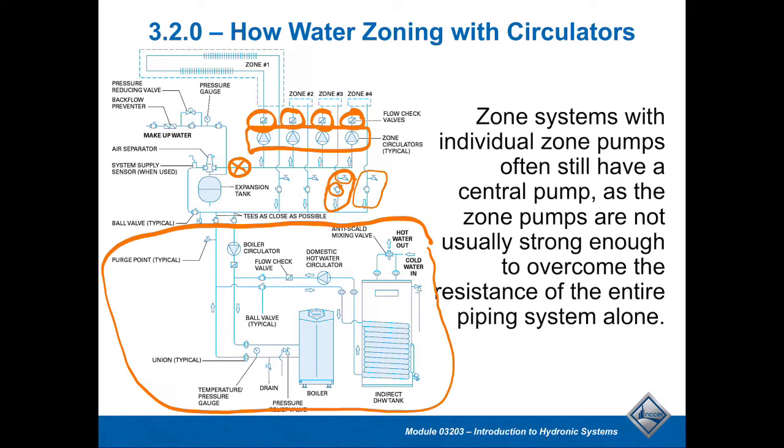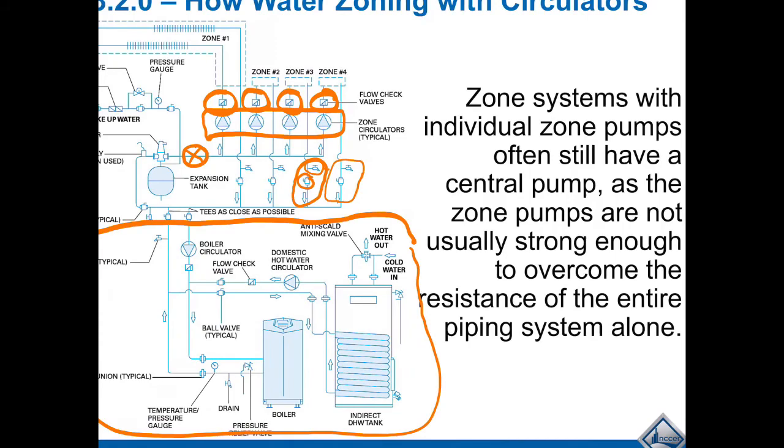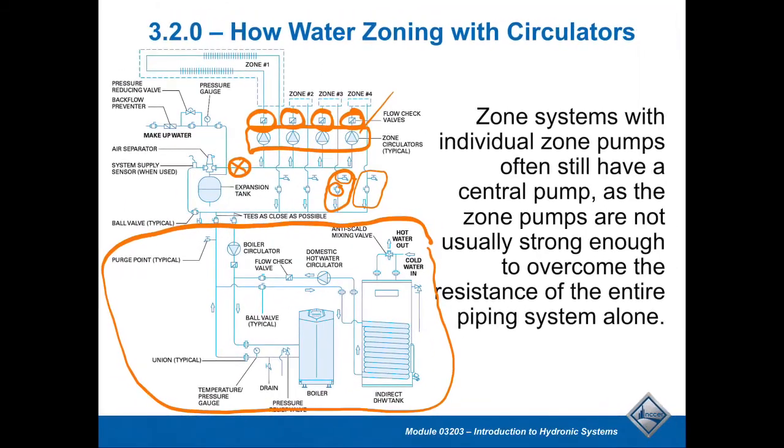One of the things that I usually look at for the zoning pumps, if I'm going to do zoning pumps, is that maybe the zones are big enough, and with all these zones, maybe I just can't get a pump reasonably priced that's big enough to do it any other way. This is a very, very nice way to do it, where I can just do it with zoning pumps in there. So it is a nice system. It's a decision you have to make, what's going to be most cost effective on that system. So that's very interesting, very typical on here.